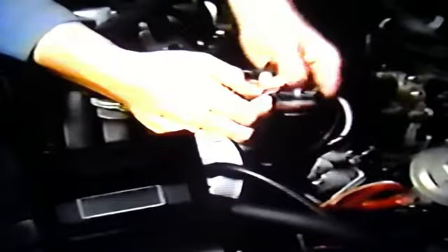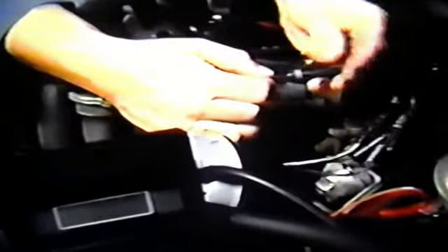For this procedure, you'll need a high impedance digital voltmeter and 3 jumper wires. Our test lead is a factory-made rig that plugs into the TPS at the carburetor and into the computer connection. The sweep test is done by hooking the high impedance voltmeter between the blue and black wires. You connect to blue and black on all GM throttle position sensors.